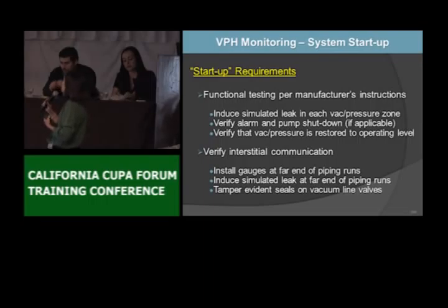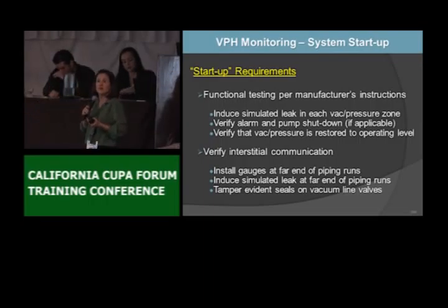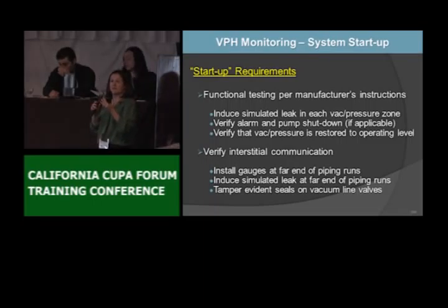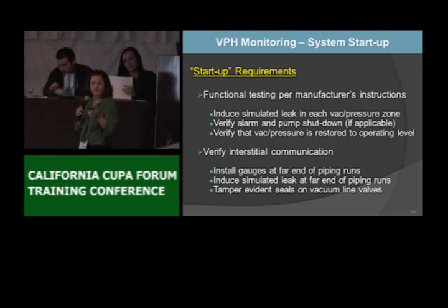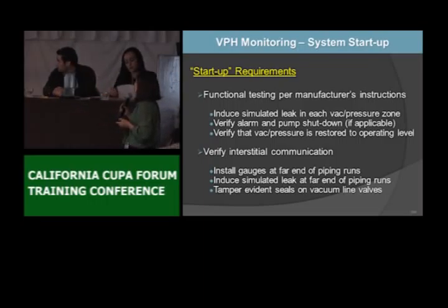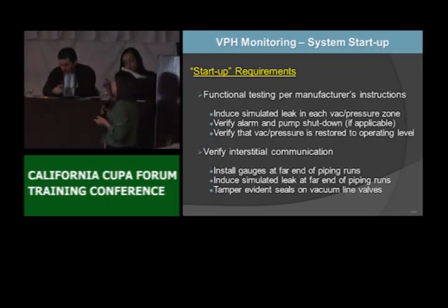And then, of course, after you do your simulated leak, you want to make sure that you bring that vacuum or pressure back to the all functions normal setting, within those set points, so that it's not an alarm. And then, of course, you want to verify interstitial communication.